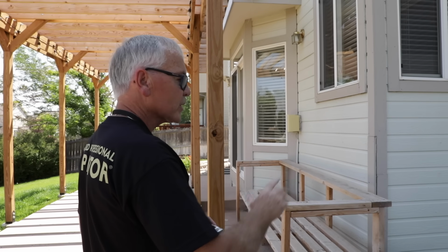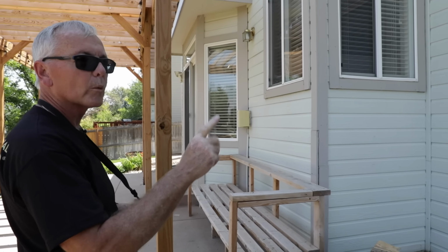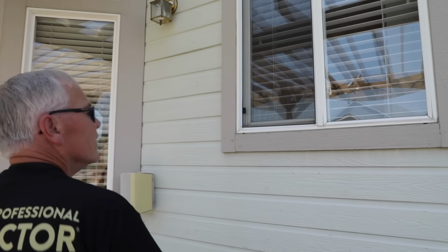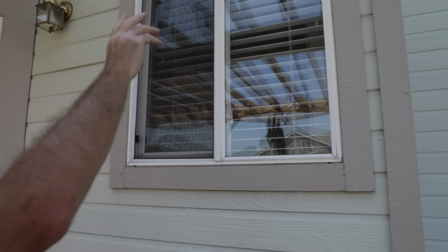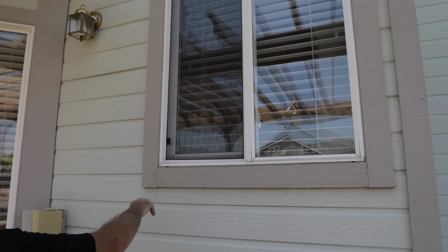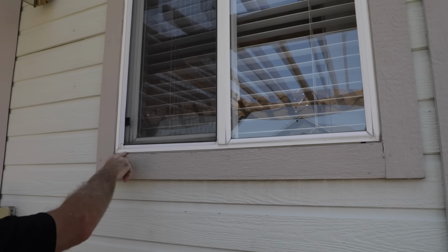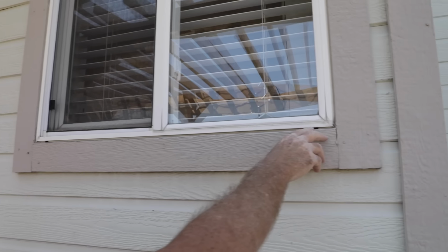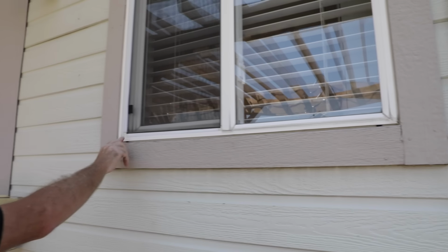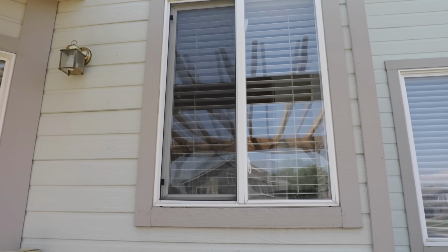Let's go ahead and move on to another one. So we're going to move on to the next side, and remember we're doing a representative amount of windows, which means approximately one window per side on the house. Again, I want to look at the frame, make sure we don't have any frame distortion of any kind. Want to make sure everything is good and tight in here, that we don't have any points for entry for water. Check our drain holes or weep holes on the bottom of the frame. Make sure we've got a place for water to get out of the track. This one looks good. So let's move on to another side.